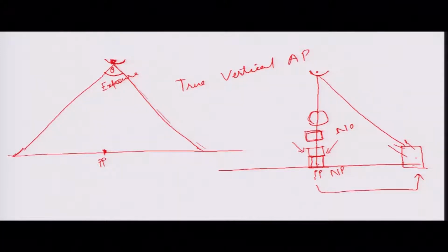And you can see this building leaning away from the principal point. In actual position it will be like this only, but because it is located away from the principal point or nadir point, it will look like this, leaning outward from the principal point.